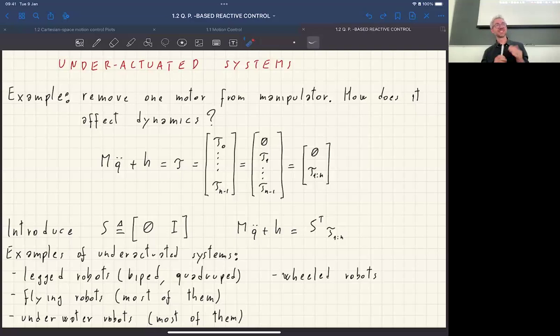It's still underactuated, but less so, because it has 4 propellers at the end effectors, right? At the feet and the hand. So you add basically 4 actuators. So it's n plus 4 actuators and n plus 6 degrees of freedom. It's still underactuated, but it's almost fully actuated. You would need to add another 2 propellers somewhere, and you could make it fully actuated.